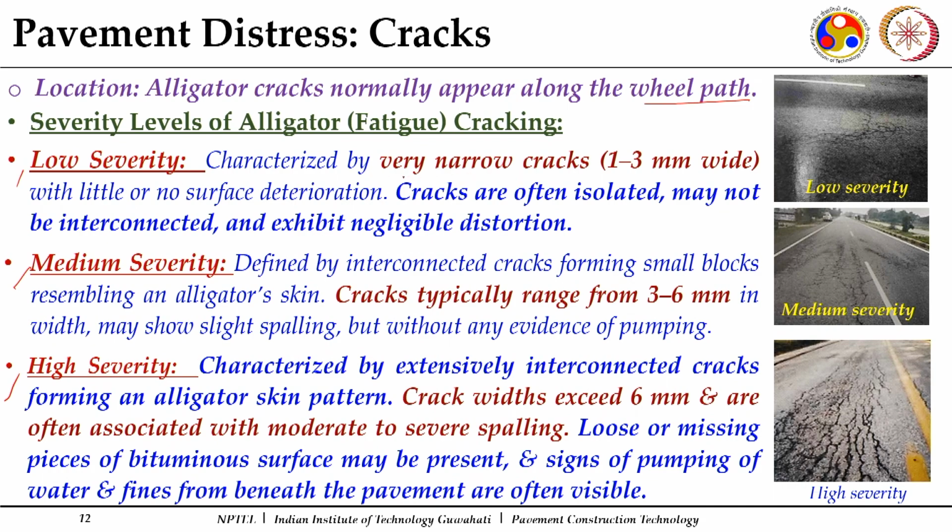Low severity is when there are very narrow cracks of width 1 to 3 mm, with little or no surface deterioration, and these cracks are isolated, not interconnected, and exhibit negligible distortion, with no change in the shape of the surface. Then we can call this low severity cracking.